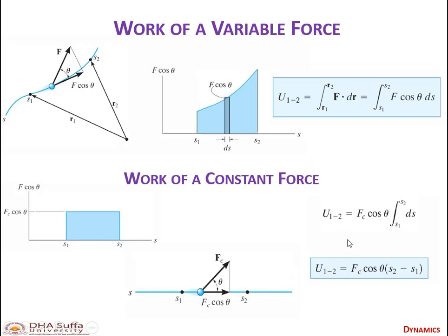So just to sum up, when you have a variable force, you need to integrate it, and the force should be a function of s. And if you have a constant force, you simply use F cos theta times delta s.